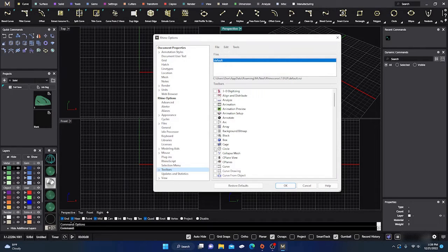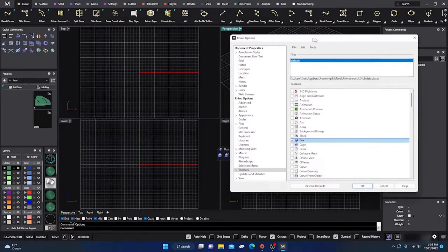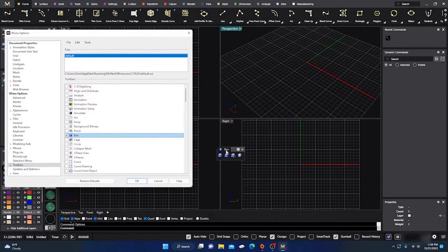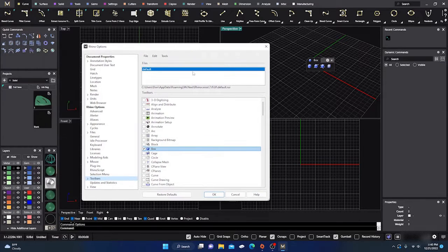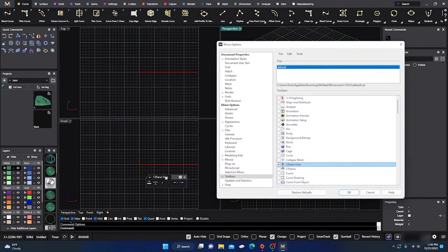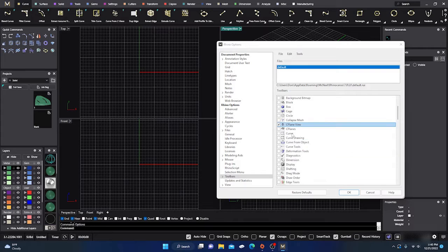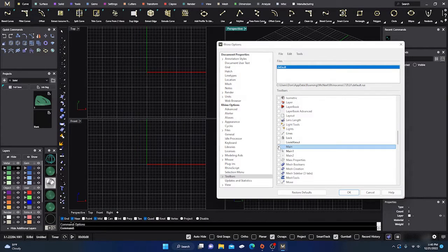You only want one, maybe box, so you can click on that and it will populate in there, and you can just keep that up there if you want, or any of them. Actually, you can just click on it and it will put it into your Rhino or your MatrixGold menu. If you scroll down to main and click on main, it'll populate all of them over here.